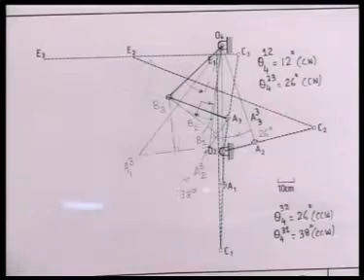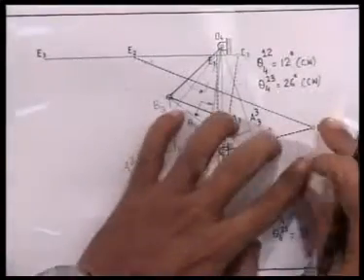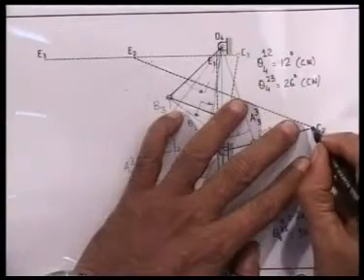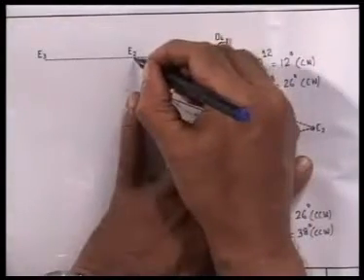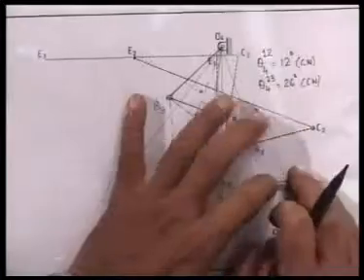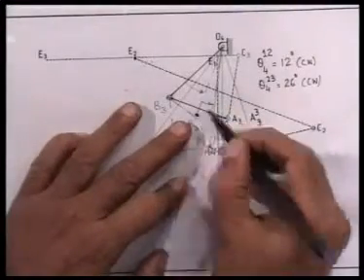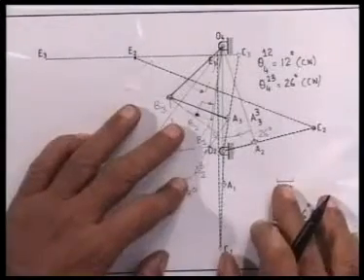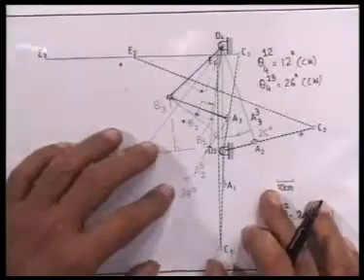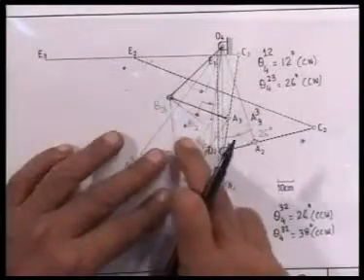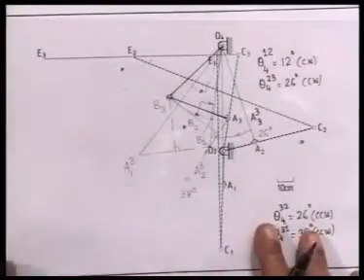We mark the relative position of the door board. Door board is completely specified by 2 hinge points on it, namely C2 and E2, and B2 is here. So we have marked, as we see here, 3 points, namely C2, E2 and B2 on this tracing paper.